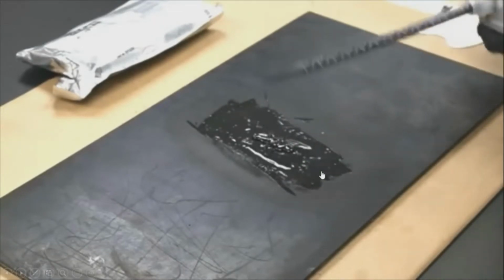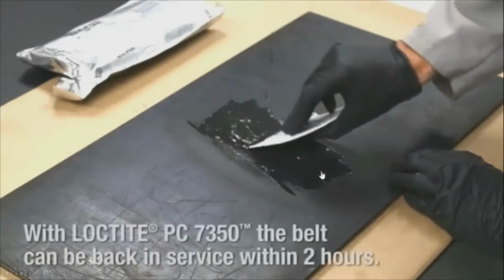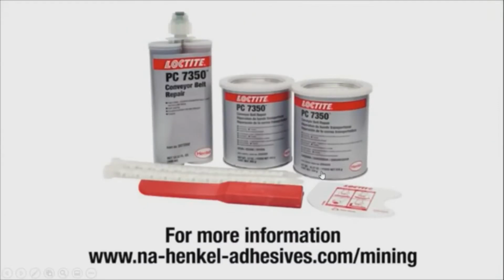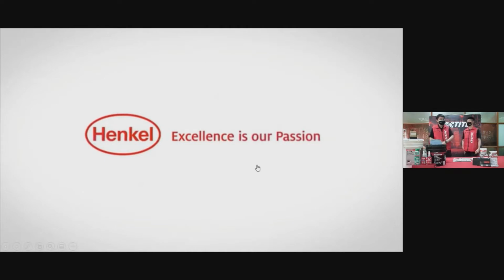After that, you can see we just apply it, using a plastic spatula to do some simple spreading of the product. Once it's cured, after probably below 2 hours, you can resume operation of your conveyor belt systems. All right, thank you, Kim, for sharing on this Loctite conveyor belt repair.